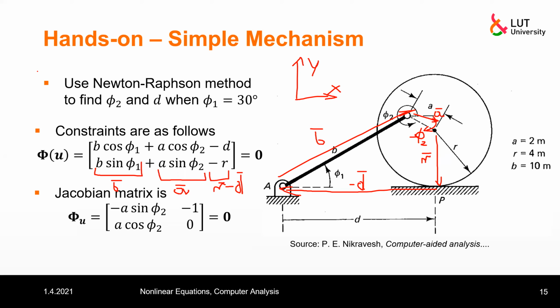Okay, so we can already see that the Newton-Raphson method can be used to provide some kinematic analysis for mechanisms. Like here, we start with one variable, and then we were able to solve it reasonably easily, because it's quite easy to form this vector equation. It's reasonably easy to get other kinematic values from that analysis.